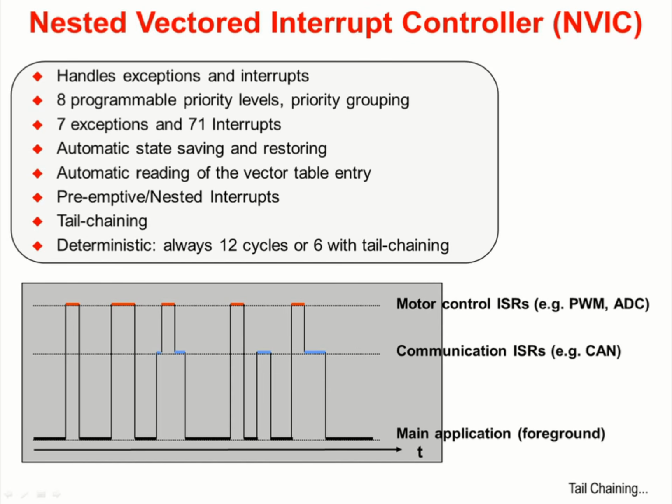When the motor control interrupt arrives, we can't wait for the communications ISR to complete. The motor control ISR must preempt it. The remaining instances are further examples. Remember that the nesting behavior is programmed into the NVIC hardware.